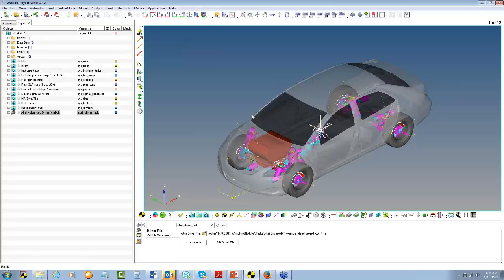Can we combine road analysis and steering analysis and run? There is something called a KNC event which does exactly what you are trying to do over here. Just run the KNC event and it combines all sorts of analysis. What is the purpose of the SDF file? That tells you all the necessary information about the suspension, so it is kind of an output. It is also an output of the result and you can gauge that.